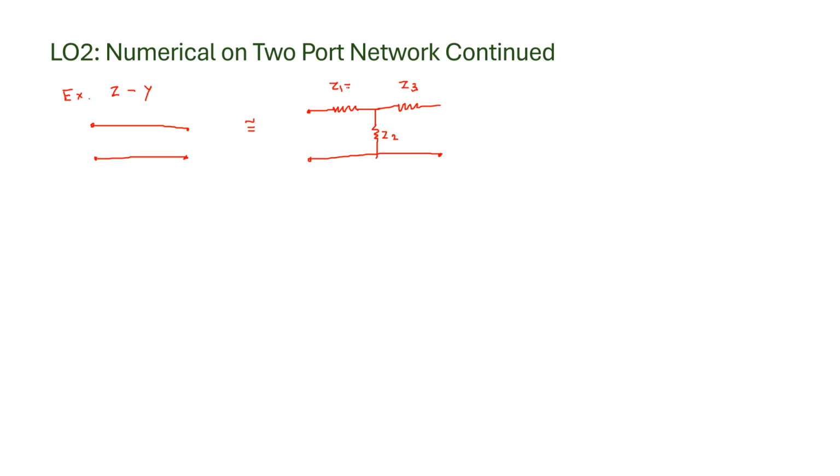Now what should be the value of Z1? Now we can see here, suppose this is my midpoint over here. Here I don't have any resistor in this part, but I have included a resistor Z1 or impedance, and now this value should be 0, meaning it is as good as a short circuit. Similarly here on this part also there is no impedance, but I have included Z3, but this value should be 0, indicating a short circuit.